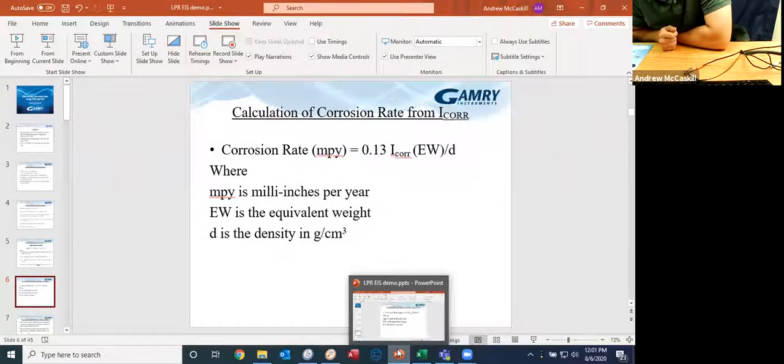Yeah, I think that question solidifies we should do another talk like this, creating Tafel plots and how to pull out what those values are. If you go to our website, or just do a Google search for potentiodynamic or Tafel plots, creating Tafel plots, you're going to find a lot of information on them, and you'll see the images of what the plot's going to look like. You can plot them a couple different ways, but that's the information you can pull out.